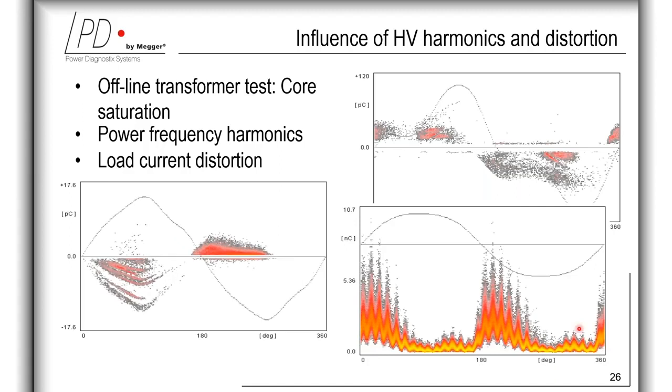And the third pattern here is showing a PD pattern of voids in a polymeric material with a semiconductive interface. The applied voltage here has a content of the third harmonic, and for this reason, it's causing this almost triangular shape of the voltage. Discharges of spherical voids under low rate of charge carrier generation directly reflect the electric field and show the wave shape and its distortions one-to-one.